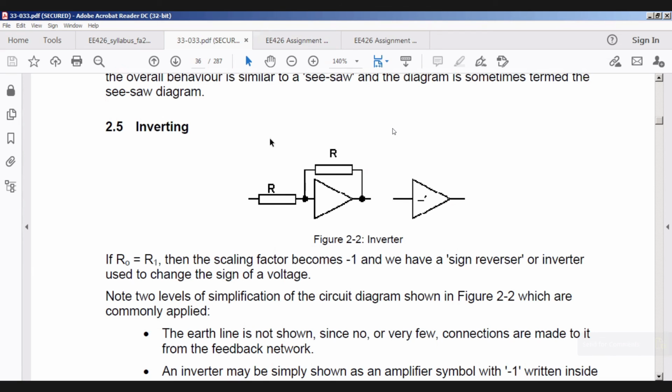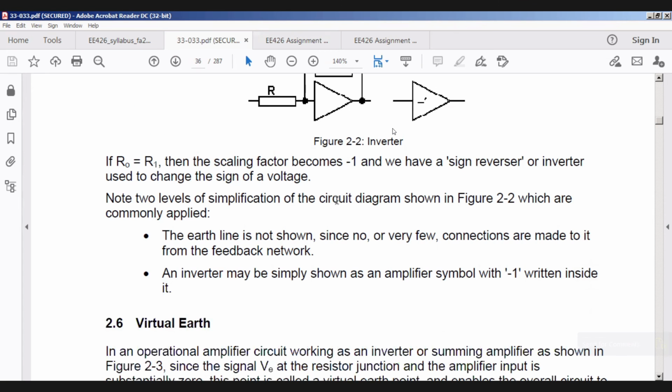It will just show you what it means to have these kinds of components in the feedback channel. All right, so this is all you need to know. Notice how, as in your question, we only have one lead here. What does that mean? Depending on the configuration, it will either invert it, integrate it, or differentiate it, depending on the component that you have on the feedback channel. But in short, you do not need to worry about this, because most of these are just functioning as inverter amplifiers.